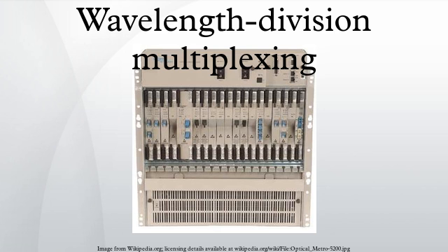Transponder. In practice, the signal inputs and outputs will not be electrical but optical instead. This means that in effect we need wavelength converters instead, which is exactly what a transponder is. A transponder can be made up of 2 transceivers placed after each other. The first transceiver converting the 1550 nm optical signal to an electrical signal, and the second transceiver converting the electrical signal to an optical signal at the required wavelength. Transponders that don't use an intermediate electrical signal are in development. See also transponders for different functional views on the meaning of optical transponders.